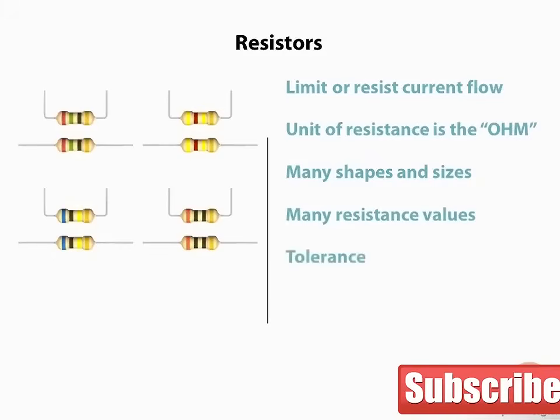When resistors are manufactured, the value cannot be controlled precisely. Each resistor has what is called a tolerance. That is the value the resistor can vary by from its face value. Common tolerances are 10%, 5%, and 1%. For example, a 100 ohm resistor with 10% tolerance could range from 90 to 110 ohms in actual value. This is not usually critical in a circuit, but if it is, choose a tighter tolerance resistor. The same 100 ohm resistor with 1% tolerance would range from 99 to 101 ohms.